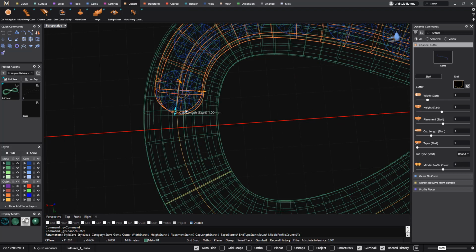As you can see, this is just following the last stone, but what we can do is change the end type. So now it's round. What I can do is cap it, that is in the middle of the stone, or flat, so it's the same that we had in round, but just where the stone ends. Or what we can also do is sharp corner if we want to add a stone. Probably for this one, I will go with the flat one.